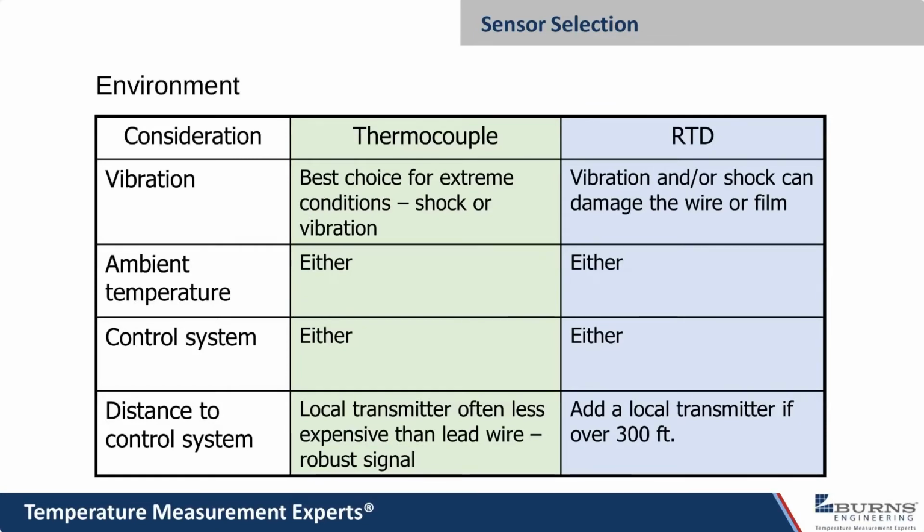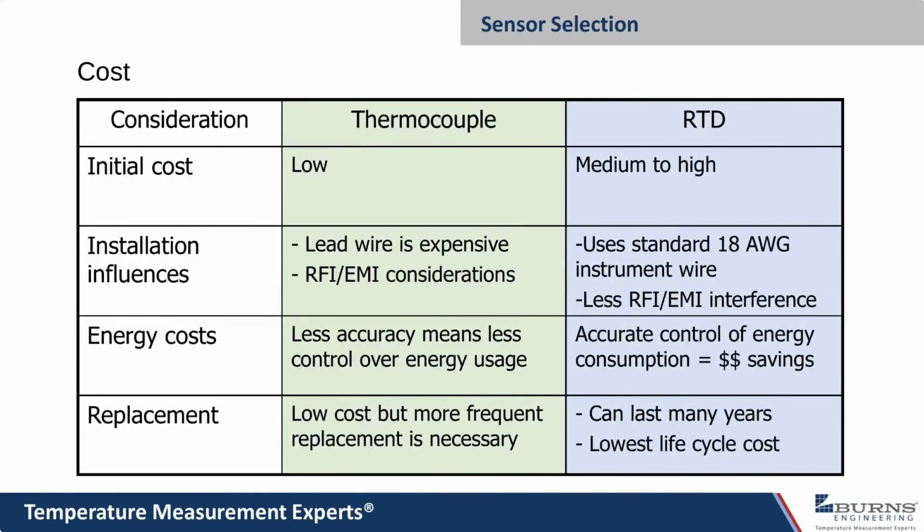The other thing with thermocouples is the cost. Sometimes the thermocouple extension wire can be a little spendy, and you're probably better off spending that money on a transmitter mounted right with the thermocouple at the process location. Here I mentioned the RFI and EMI considerations,